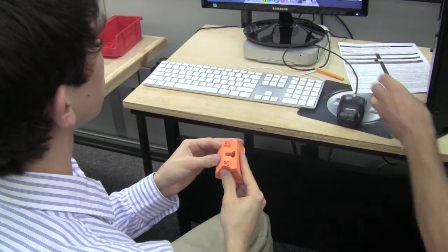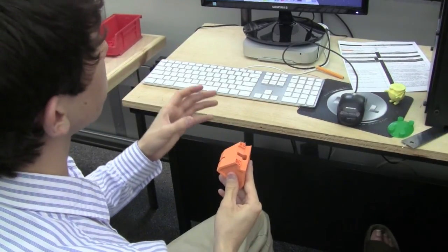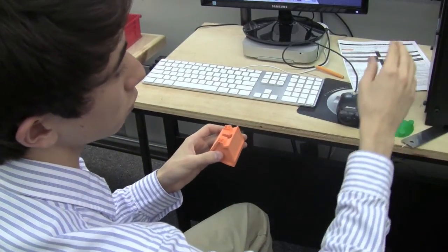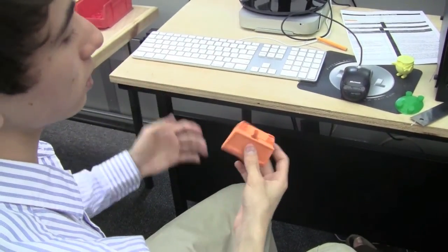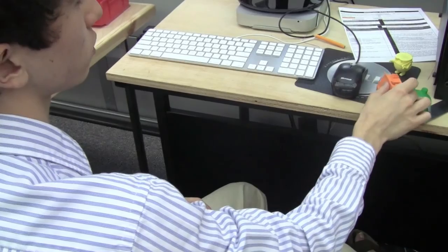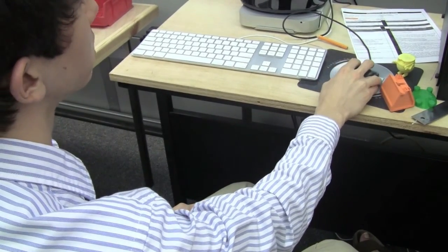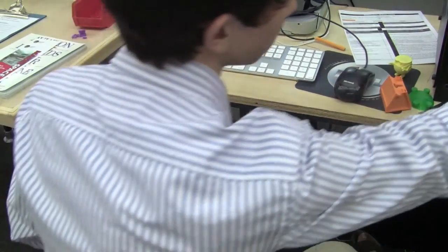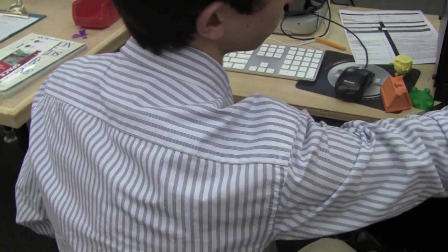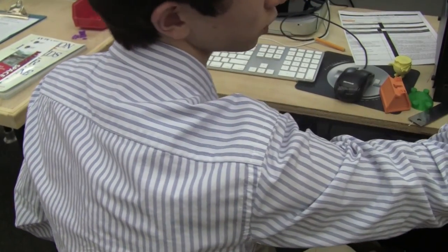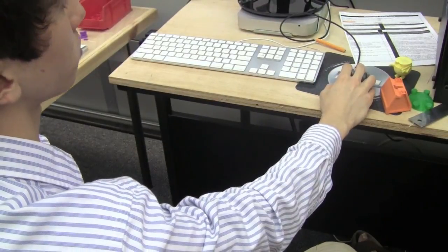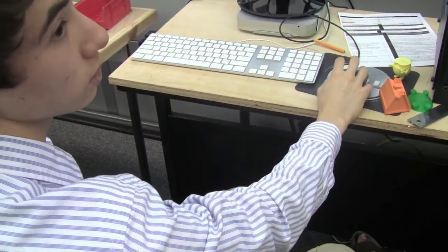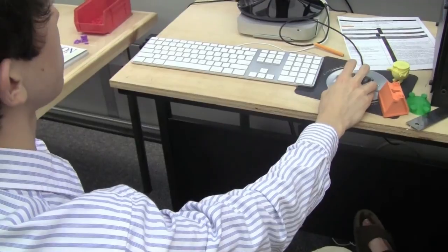All right. Next is travel feed rate. Travel feed rate is how fast your extruder moves when it's not extruding plastic. Because it's not extruding plastic, normally you can just set it to 150, which is the fastest speed. You'll actually see it when it's moving over here for homing. Once it homes and starts its print, you'll see it zips along pretty quickly, but it doesn't really affect the print. So I usually just set it at 150.